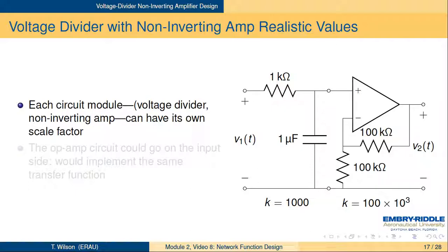There's no reason to have a lot of current flowing down that path. None's going to go into the minus terminal. So if you put big resistors there, it basically just sets up the voltage divider with very little current flow, little power. And so you're not wasting power in your circuit. Say you're running this thing off of batteries. You don't want to waste a lot of power just having current flow so you can set up a voltage divider.